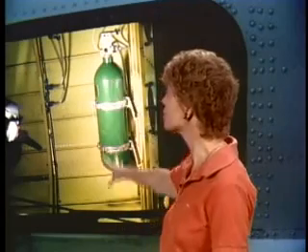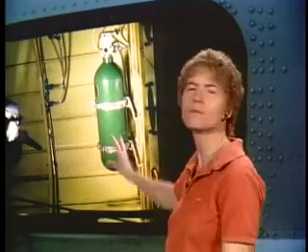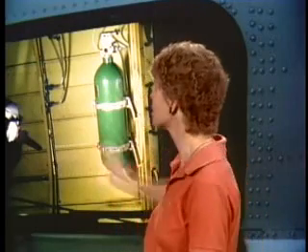Now, if you have a contaminated oxygen system, normally it is purged with oxygen. If you need to purge it, you purge it with oxygen. If you have to use something as a lubricant on the oxygen system tapered pipe threads, you do not use normal oils and greases and so on. What you can use is Teflon tape. Teflon tape is what you can use as a lubricant on the oxygen system pipe threads.